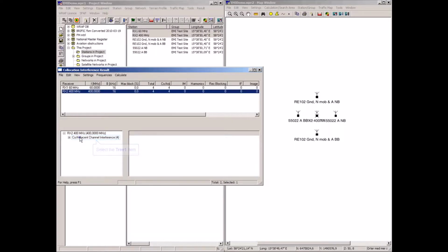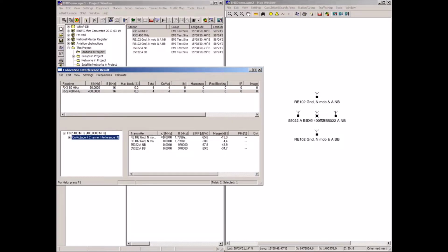And at 400 megahertz, it's also bad. But it can be seen from here that in order to have a reasonable chance of good reception for the military situation, with computers being in a staff headquarters, for instance, quite near the receiver antennas, an EMI standard of the severity or stringence of MIL standard 461 should be selected.